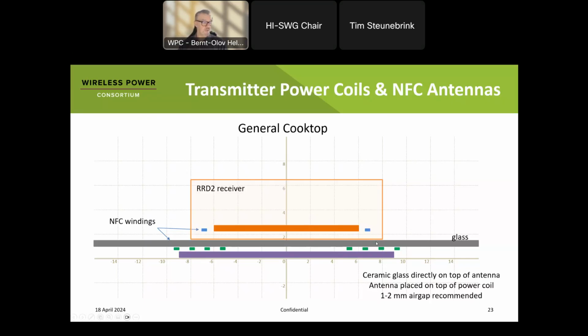This is just to maintain the good coupling between NFC, less depending on the positioning, and also making sure the power delivery works. There's quite a lot of freedom there in positioning. It's generous in all directions, and it's not limiting the functionality, neither the communication nor the power transmission. It works quite well. You don't need to be that exact to position things.